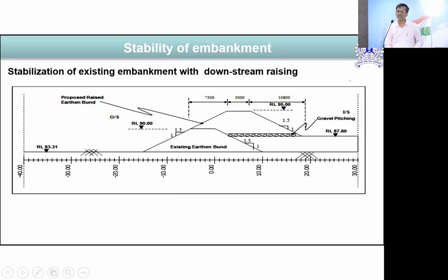But I cannot ignore it, because if it is weak, the pore pressure will rise or the strength will reduce, and that becomes a vulnerable point where we cannot find out information. When in situ testing, even cone penetration, cannot be done, we can go for geophysical exploration. Geophysical exploration is non-invasive; it will not penetrate through it. So these are some of the aspects of finding out the parameters.